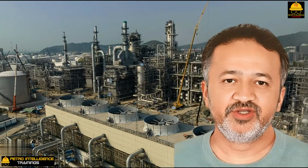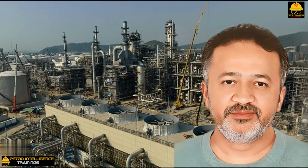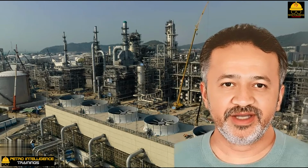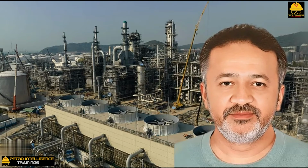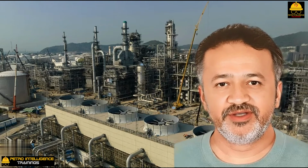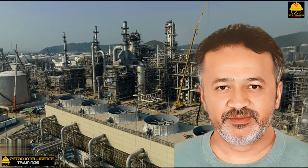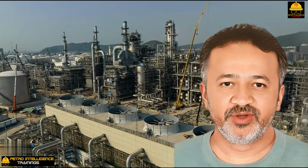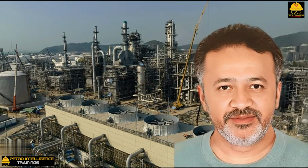Fin deterioration. The fins are usually made from aluminum. Especially in moist, steaming environments, the fins are subject to destruction by corrosion. A corroded fin retards rather than promotes heat transfer. It's easy to break such fins off by hand. A high-pressure jet of water can be used to knock off the corroded fins and partly restore cooling capacity.